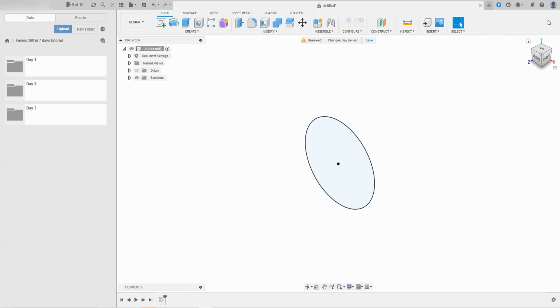And now in order to use the Loft command, we actually need to create another sketch that is on a different plane than the regular default planes that we normally sketch on. And we can use construction planes to do exactly that. Construction planes allow the user to input a plane in reference to the default planes or another 3D object to give additional surfaces to draw and sketch on. This can be particularly useful if the elements we are using don't align with the default environment.